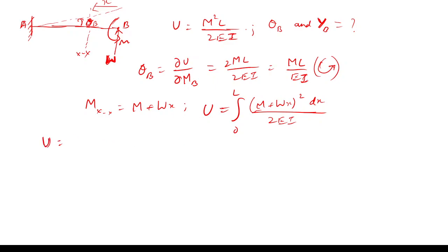I can integrate this after expanding it. 1 by 2EI I have taken outside. Only after the integration you have to put the dummy force equal to 0.